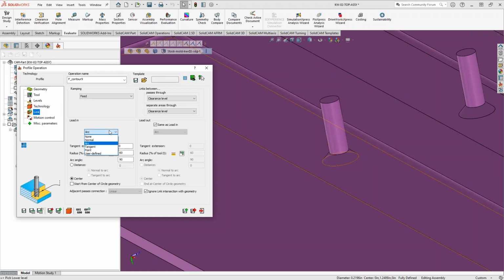And then for my link, I like to use profile or HSS because you get more control over the lead in, lead out. So in this case, I can easily control this. Let's just put in another 30 thou in there, save and calculate.